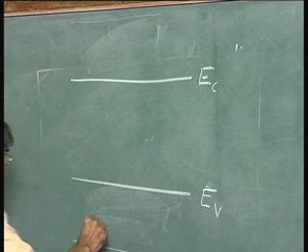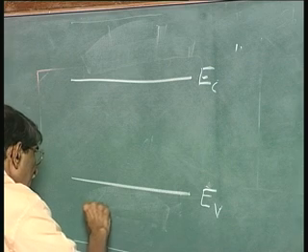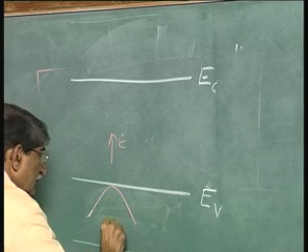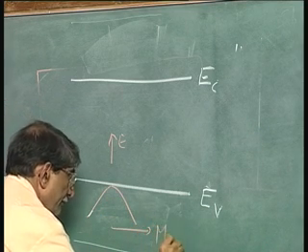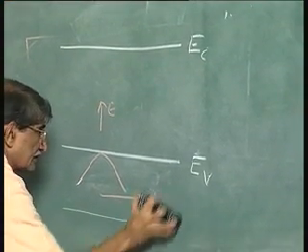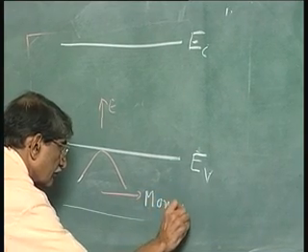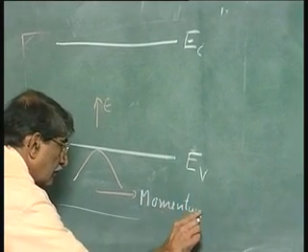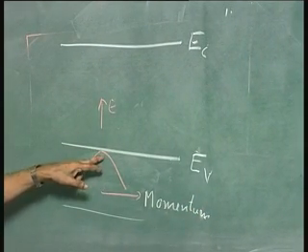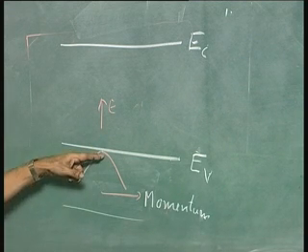I can just say, in the case of gallium arsenide, that curve, the energy versus momentum. I show only one curve. So, what is important is where the tip is, because the holes will tend to occupy this position, top of the valence band.